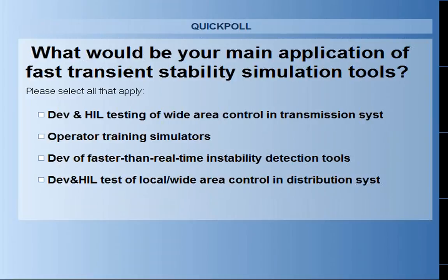We model the power grid either in positive sequence, as it is customary for transmission system studies, or in full unbalanced three-phase when we want to model a distribution system. And as I mentioned before, the time step then for the simulation is in the range of a few milliseconds.